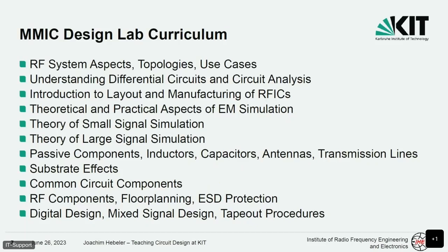Another big part is teaching them how their tools work. We try to teach them how does an EM simulator calculate this EM simulation, how does the circuit simulator calculate a DC solution, or the AC solution, or what is harmonic balance. Because what we see in our practice as PhDs is that we push these tools to a certain limit. And we're talking about Cadence and battle-tested tools, in a way. Even these tools will at some point produce strange results: oscillations where there shouldn't be, some weird drift, convergence issues.